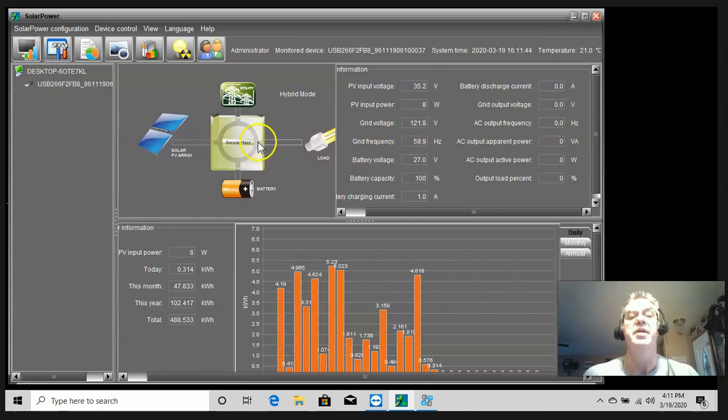But this is acting as an on-grid inverter, so what little power is coming in is supplying that leg. Right now I'm only on one side, because the way these are set up, you have to get 2 of them if you want to put power to 2 legs. But one leg of my house is getting assistance from what little sun power is coming in from my panels.